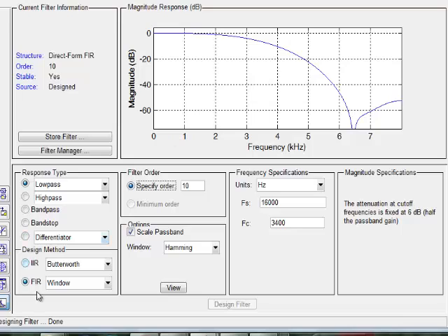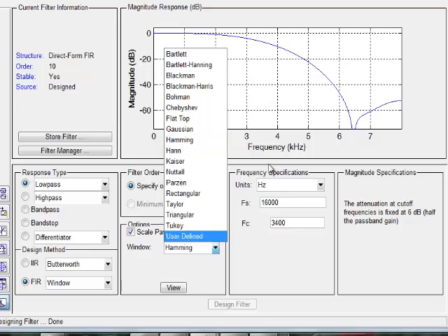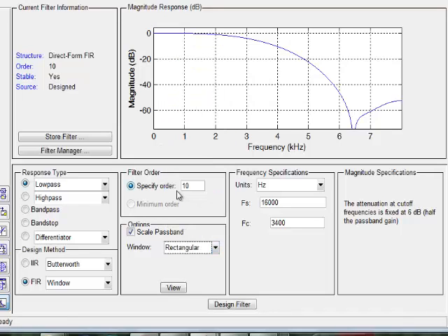The point is that if you use the FIR filter, you see that here, for example, with order 10, it's not that sharp. It starts to attenuate, and the attenuation goes to almost minus 70 dB, but then starts to increase again. This is the smooth one, but if you use, for example, a rectangular one, then you will definitely have a lot of fluctuations, these side lobes, which are because of the Gibbs phenomenon.